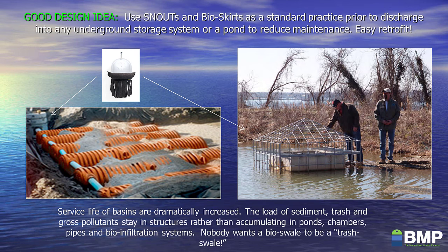In fact, the overburdening of an infiltration practice can reduce its service life. So getting stuff out upstream, especially for underground systems, is really important. Structures with snouts or hoods and bioskirts prior to discharge into these storage facilities should be a mandatory practice.